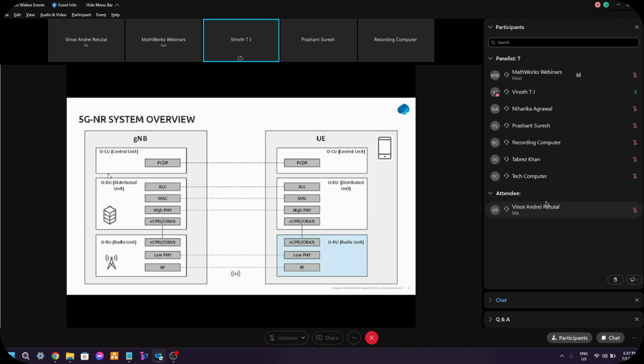In the radio unit, we'll be having the Lo-Fi and all the RF related activities, like digital front-end processing, and the interface towards the RFICs will be sitting inside the FPGA. It can be either FPGA based or an ASIC based solution. Now the ASICs are also evolving for small cell based applications for the radio unit.